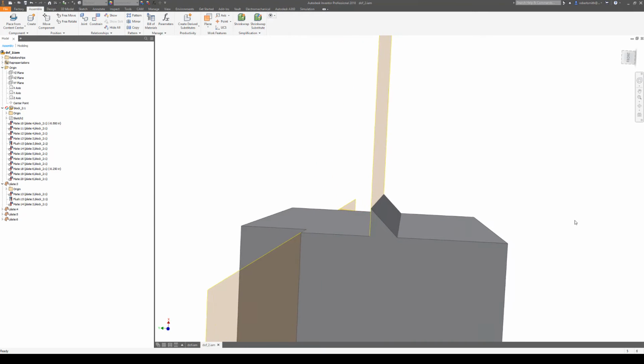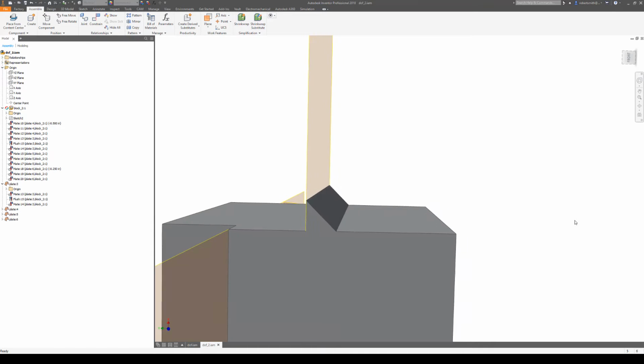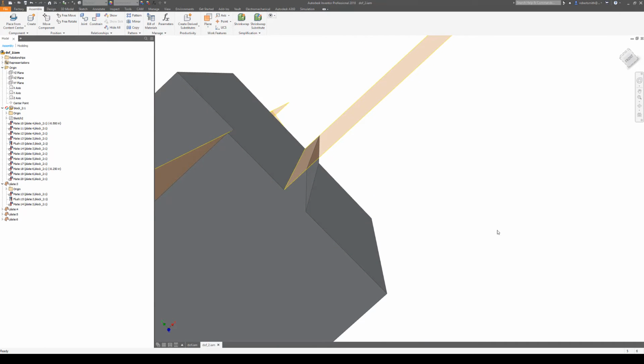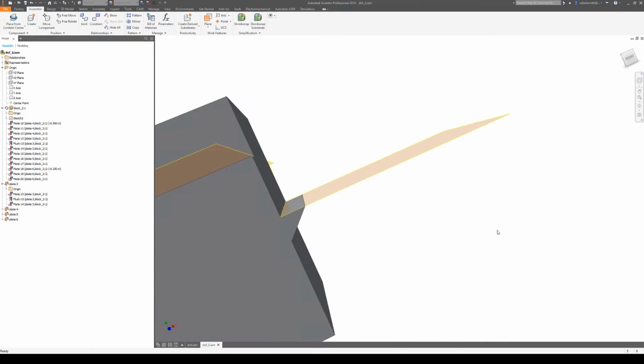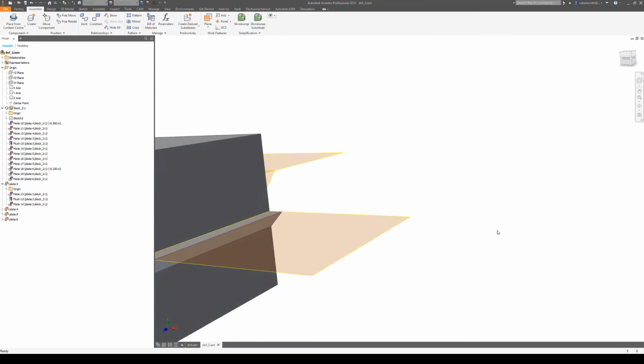We do frequently discourage trying to model weld beads in FEA simply because you're oversimplifying what is a very complex problem. The weld beads tend to be a lot more complex than what we've shown here, but that doesn't preclude you from including them in the model if it's really only there to help join dissimilar element types like we have here, or even spread out forces and spread out stresses to avoid concentrating stresses at a single location. You can put your weld bead in there, and it's basically effectively putting in a step, right, where we can overlap the shell elements with the tetrahedral elements.